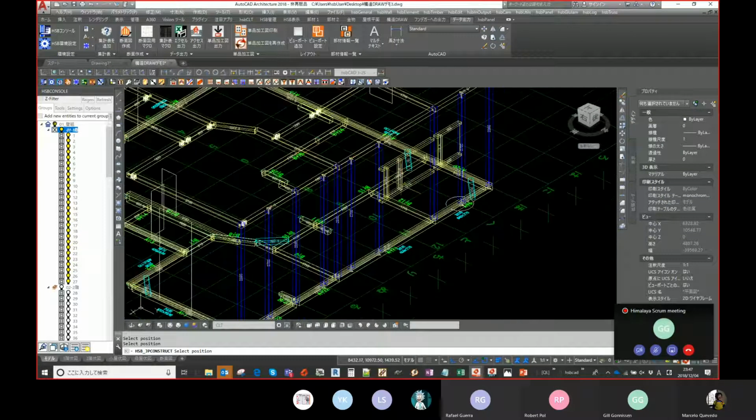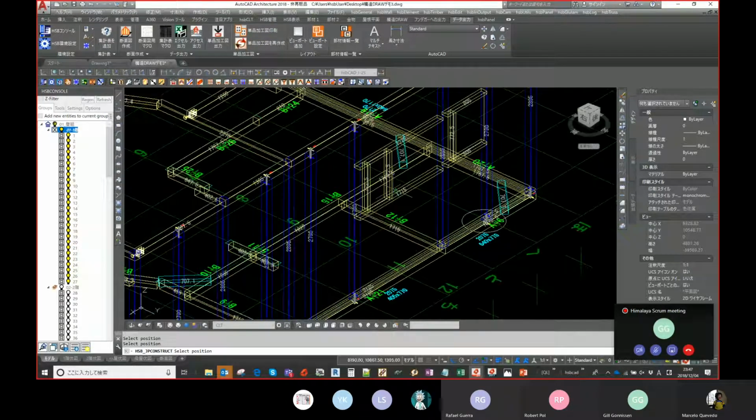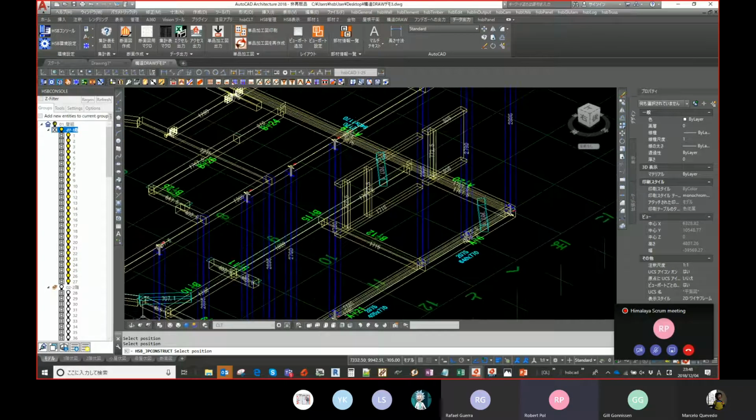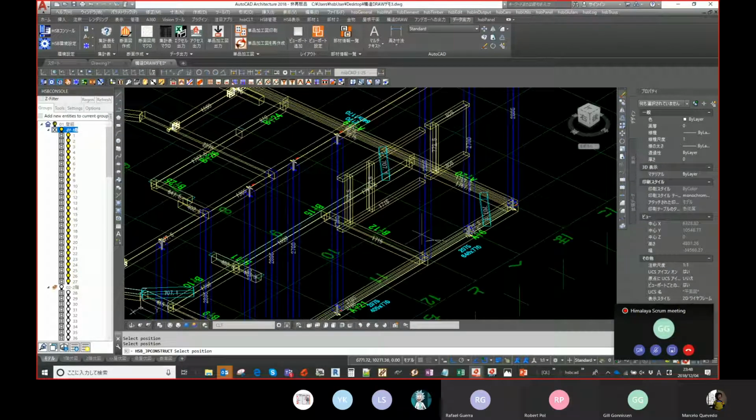So the posts play an important role in this system for structural. And also the posts extend through to the top plate, and normally on elements it would be on the top plate, and the top plate would carry the forces to the studs too. Oh, and in this case it doesn't. Some do and others don't.